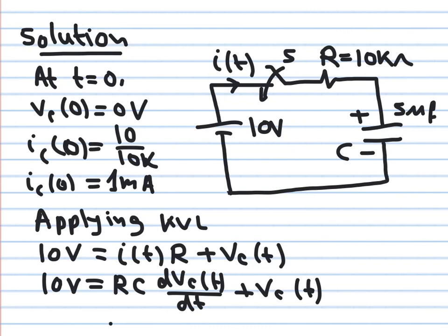Okay, so at time 0 we know that the switch was opened before time 0, the battery is disconnected from the circuit, this one has 0 volts, then we know that everything is stable. Now you close the switch. Immediately after you close the switch, and I'm gonna correct myself here, I'm gonna write it as VC of 0 plus. By VC of 0 plus, I mean the value of the capacitor voltage immediately after I close the switch. It must also be 0.